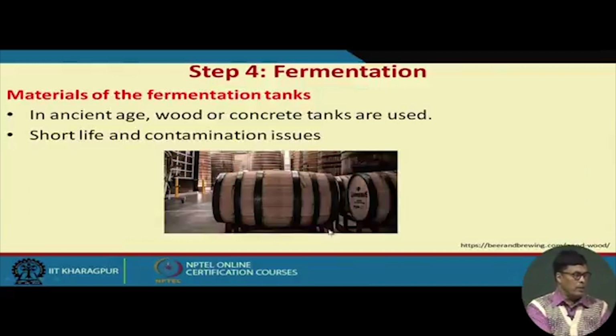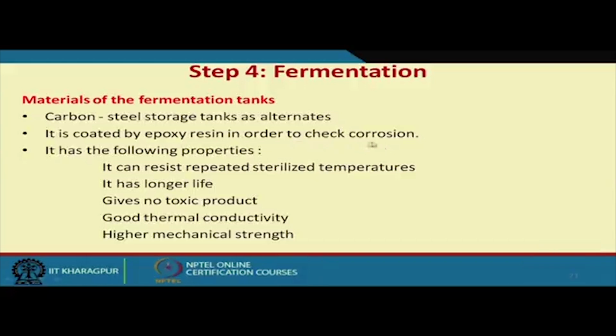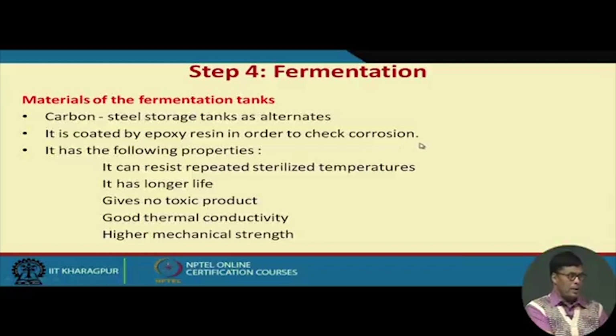Now the material of the fermentation tank: in the ancient age, wood or concrete tanks were used, with short life and contamination risks. So nowadays we use stainless steel or carbon steel storage tanks as the alternative. They are coated with epoxy resin in order to check the corrosion. Epoxy resin is largely used in the fermentation industry. It protects the material of construction from acid attack.